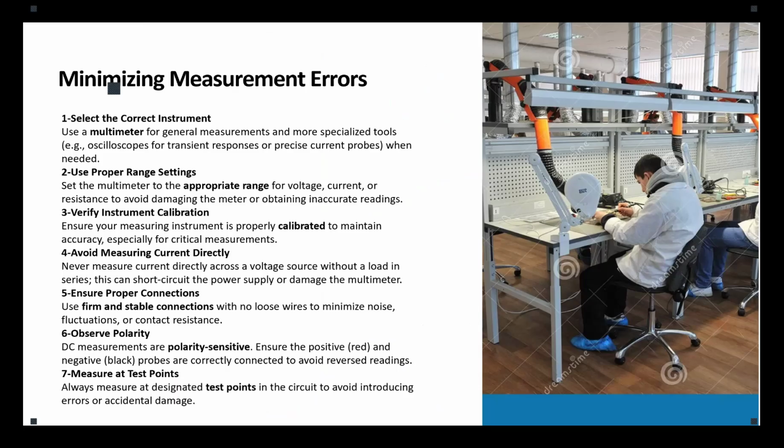They are like standards that we should use. We kind of consider that already. Now, how you can do that is you have 17 stations in there. You can work with each other, borrow your friend's multimeter, and see if they match. You know what I'm saying? We already calibrated those devices. But if you want to do that by yourself, borrow one, or use an oscilloscope. When you know the current, you are measuring the current from the multimeter, you are seeing the voltage on the oscilloscope, and you can calculate the resistance. So you have multiple measurement devices that you can use and compare to see which one is more accurate, for example whether the oscilloscope is more accurate than the multimeter. So you can use that as a reference to calibrate your multimeter error.